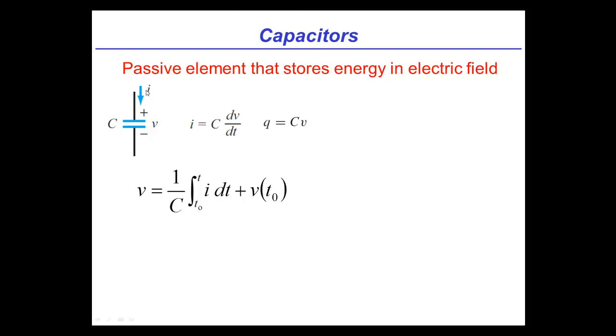If you think about this capacitor, what I did was to charge it up, I put positive charge in on one plate that induced negative charge in the other. So when I'm putting positive charge on one plate, in other words, current is flowing in, and my other plate is inducing negative charge, I effectively am allowing current to flow through the capacitor while the voltage builds up. At some point, the voltage will build up high enough that, let's say, I'm no longer able to put current in, and it'll sort of max out for the given voltage and current that I've applied.